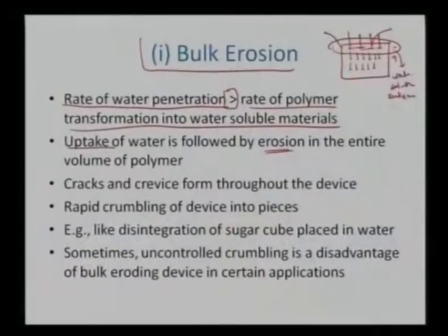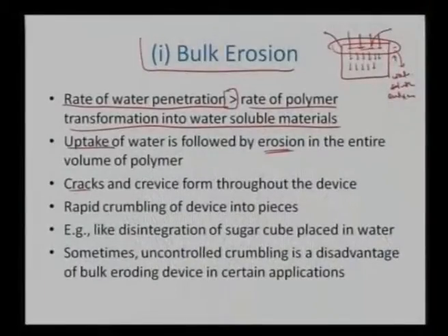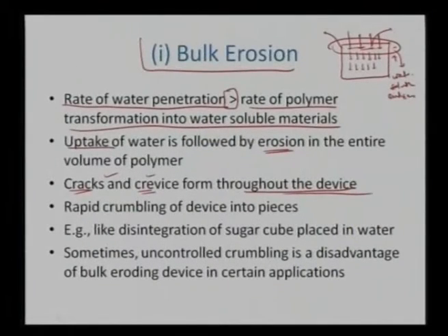So as soon as the material turns into a water soluble component, it leaves a certain pore, crevice or crack. So now these cracks and crevices start developing throughout the device, because the process of water penetration is much faster and the rate of dissolution of this polymeric material into a water soluble component is much slower. So with time we start seeing cracks and crevices throughout the device, and that leads to the rapid crumbling